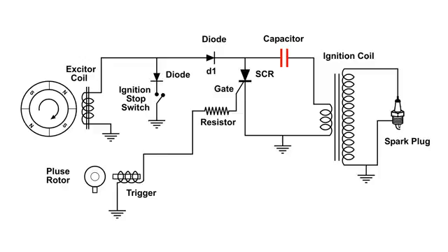When the magnet continues to rotate, we don't have any current, but notice that the capacitor is still charged. And when the magnet is in this configuration, we've got the opposite polarity, and still nothing happens because the diode will only conduct in one direction.